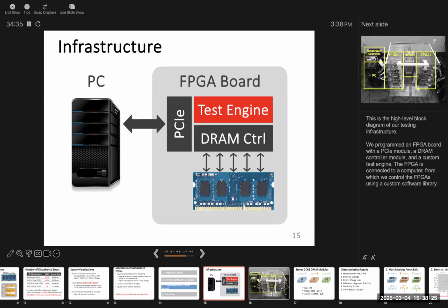The FPGA gives you this flexibility: you can program it to work first as an x86, but then one month later, you can say, okay, I want it to work not as x86 but as an ARM processor. So you can program the FPGA to implement the ARM processor. Or if you want to implement MIPS, you can simply program it to run the MIPS processor. Okay.